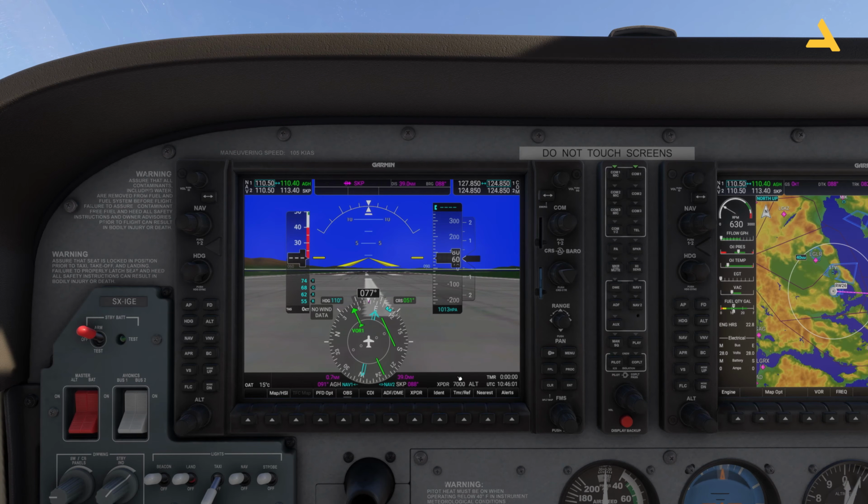So now let's prepare the plane for the flight and just press this button heading, and you can see heading. So once you take off, you will be following this heading. Let me just adjust the course again. That's it. And this course is also correct, and just keep it over here, because if I move into this option, then the plane will be actually following the GPS. It will not follow the VOR. So I will just keep it like this.